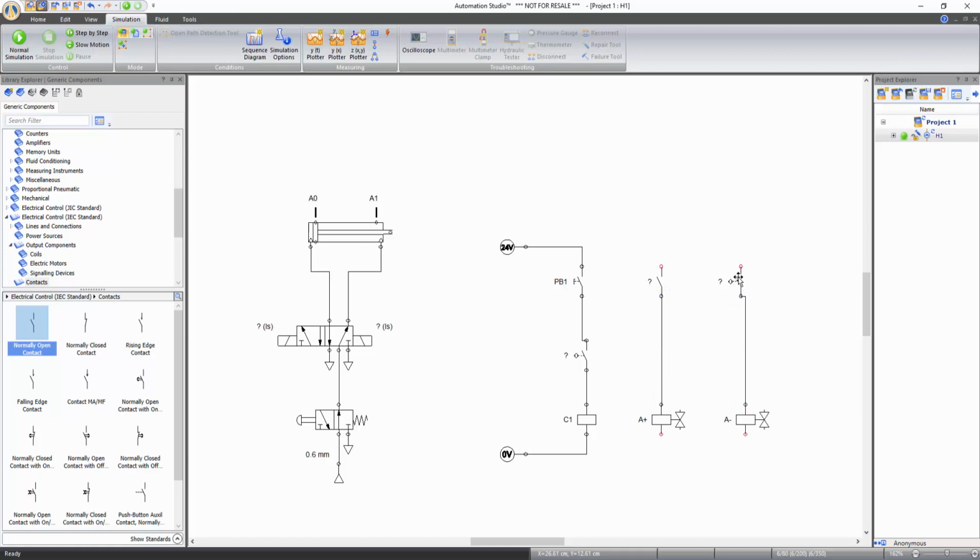You can rearrange a component's position by hovering the cursor over a component and moving the mouse while holding down the left click. While tracing a line coming across another line, there is no target sign that usually allows you to make a connection. Therefore, you need to double-click on the line to make a junction. When a 3-line junction is created, a filled black connector is automatically created at the junction. Similarly, connect the other components by inserting junctions.